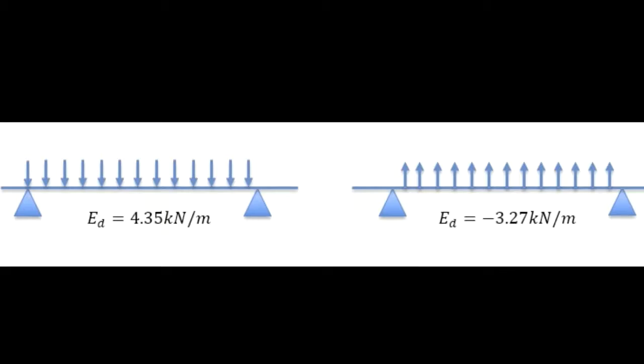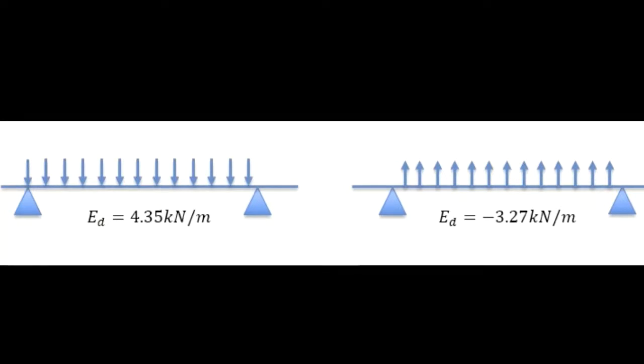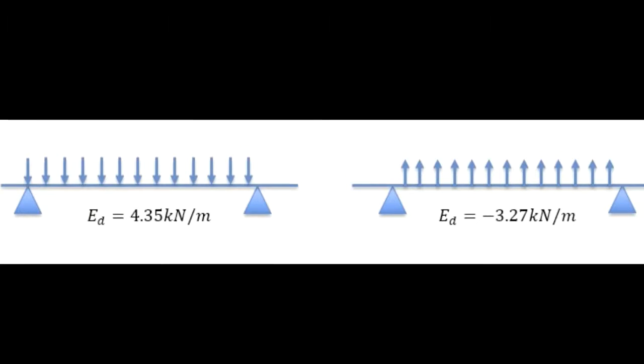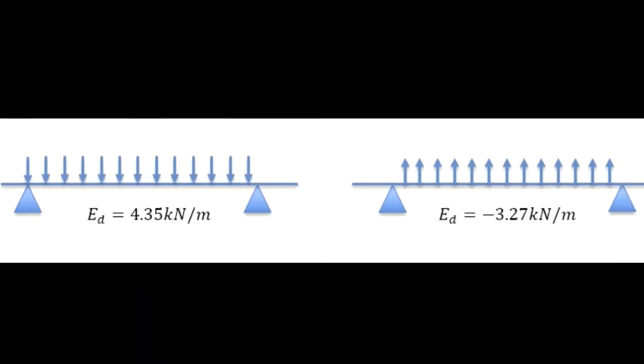Designing the girts requires the same process that was utilised when designing the purlins. The only difference is that the wind pressure on the walls must be calculated. The walls of the shed will feature the same cladding as the roof, and it will also have the same insulation as found on the roof.